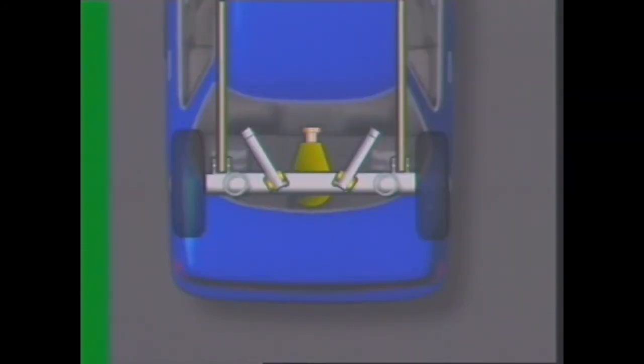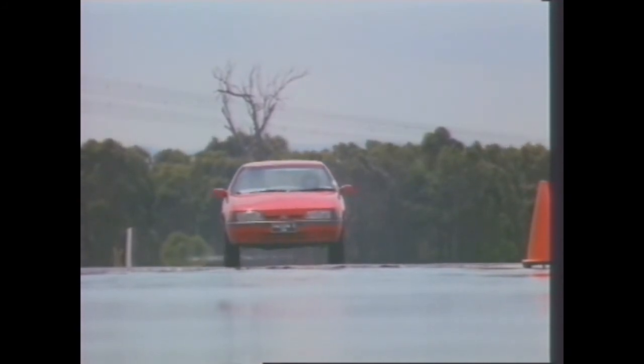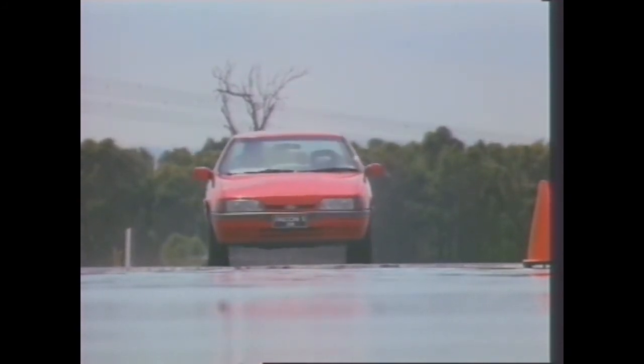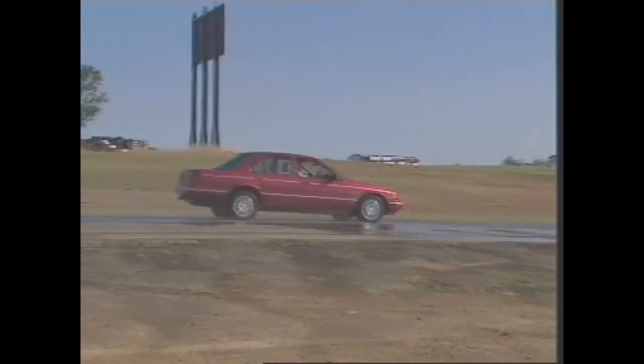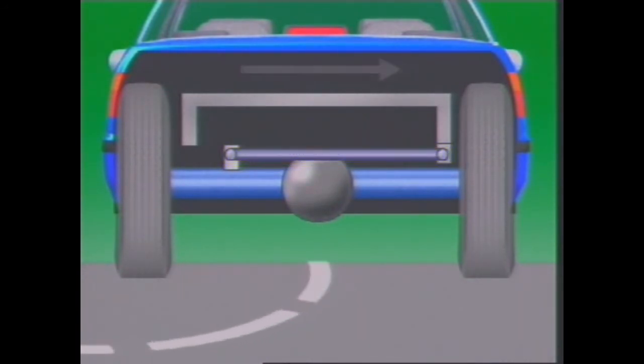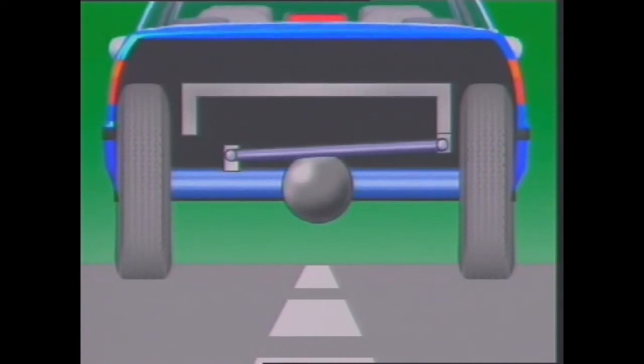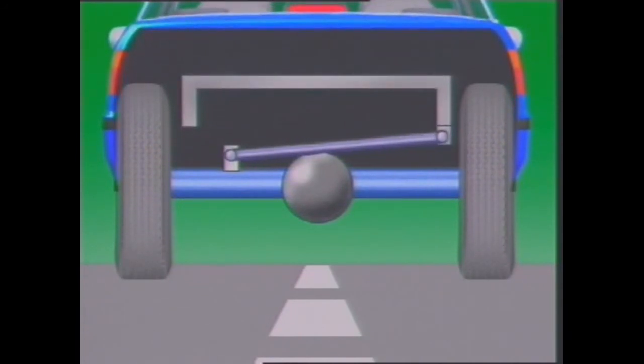This suspension system uses angled upper control rods to limit lateral movement of the rear axle during cornering. They also absorb the torque reaction forces, which limits rear axle wind-up during accelerating and braking. A panhard rod may be used to restrict lateral movement of the rear axle during cornering. It has bushes or mountings at each end where it locates on the axle and frame. This allows for variations in load while maintaining correct alignment.